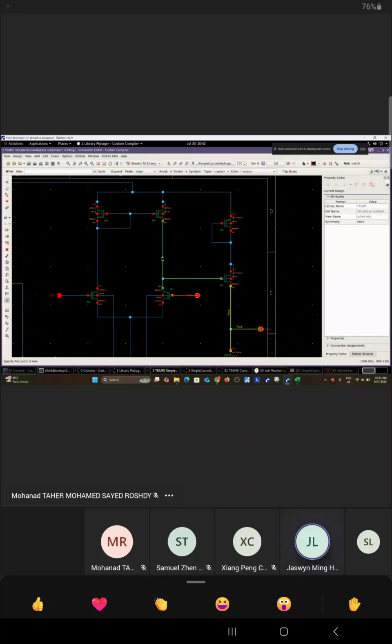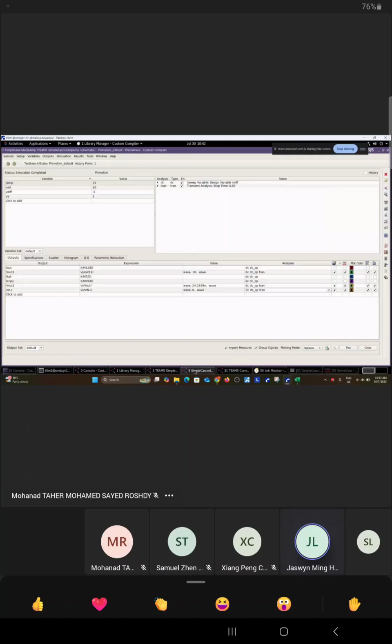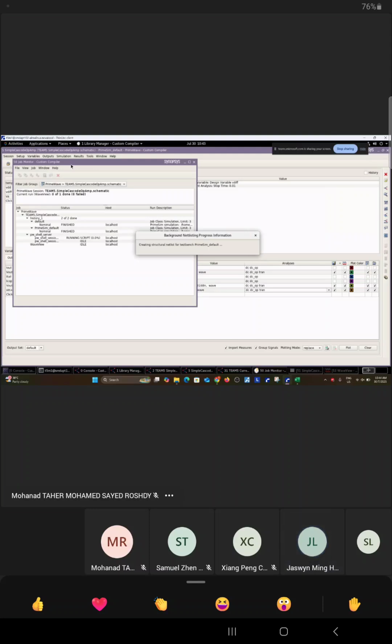In fact, even though they say there's no golden answer to the design, based on the many limitations they give you, it is believed to be the golden answer for the architecture. They already mentioned a few times to us that they don't want the circuit to be too complicated. They want a very simple circuit, so I don't think they will reward us if we do complicated stuff. This means I think folded cascode will not be viable here. We don't try to do that.